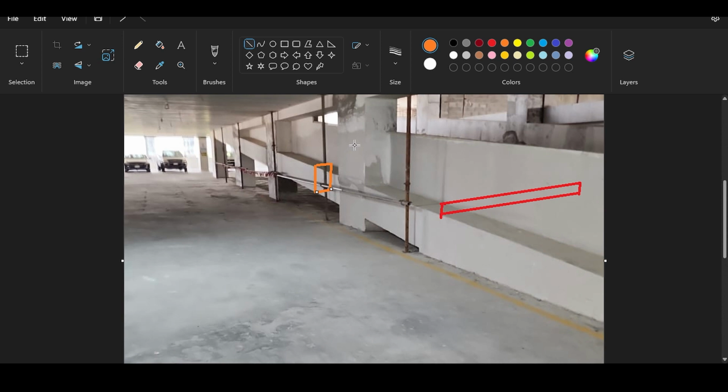Now, of course, the question here is, how would you construct that? Notice that we are doing modeling, analysis, and design of structures, so I don't even need to explain how it's constructed, but since we are here, why not explain that? You see, the construction of a car ramp is really a tedious task. The idea being that you would have to cast your columns in stages. Like here, you would have to cast your column all the way up to the level of the car ramp, and this needs setting out by a surveyor. You cannot just wing it.